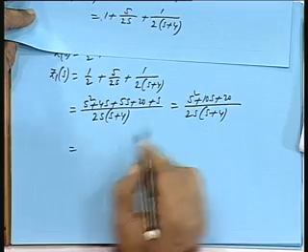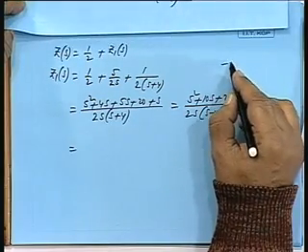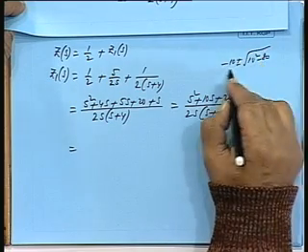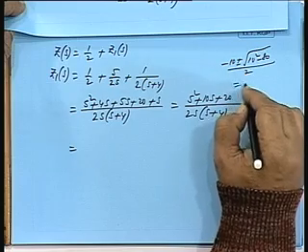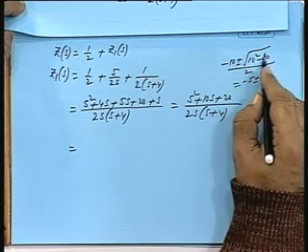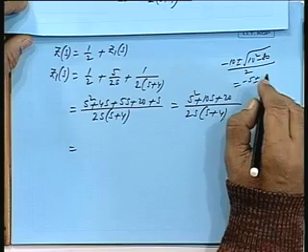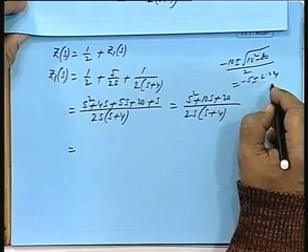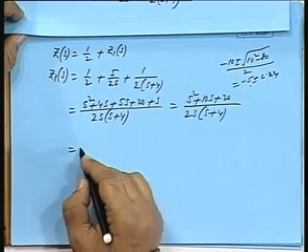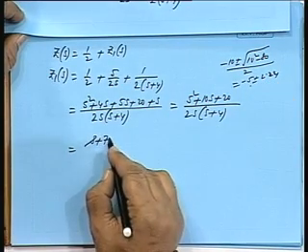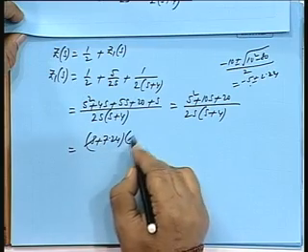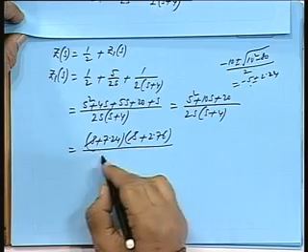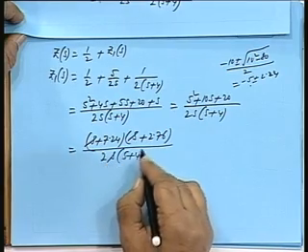Okay. So, that gives me minus 10 plus minus root over 10 squared minus 80, by 2. So, that gives me minus 5 plus minus root 20 by 2, root 20 is how much? Root 5, so 2.24. Okay. So, it is s plus 7.24 into approximately s plus 2.76 divided by 2s into s plus 4.